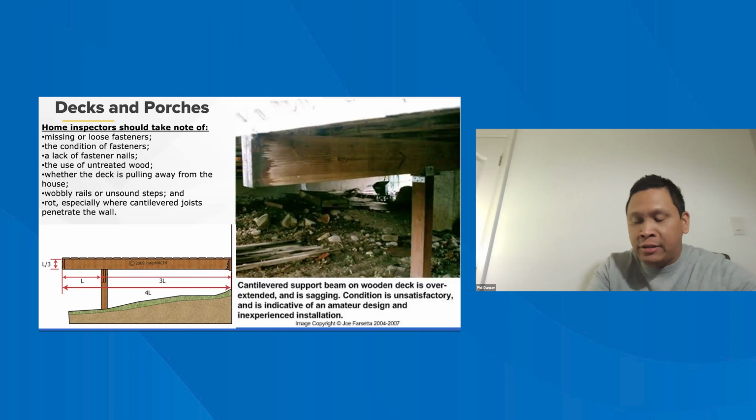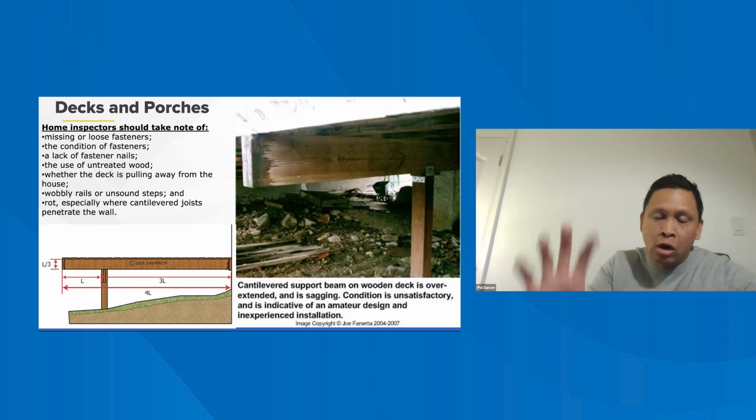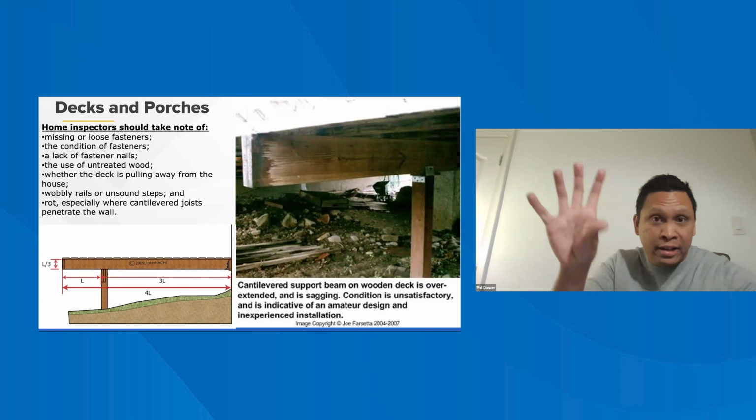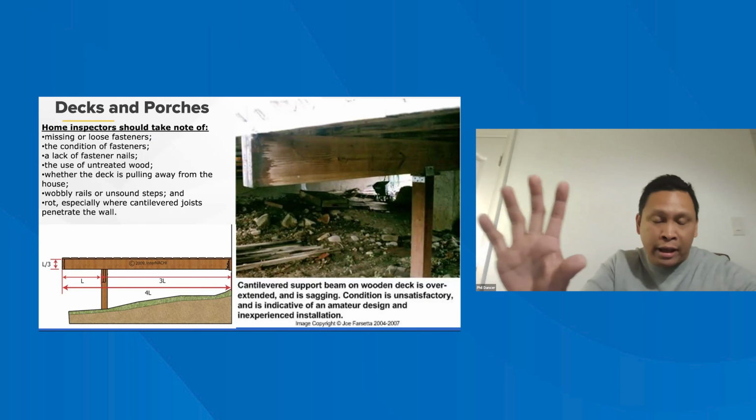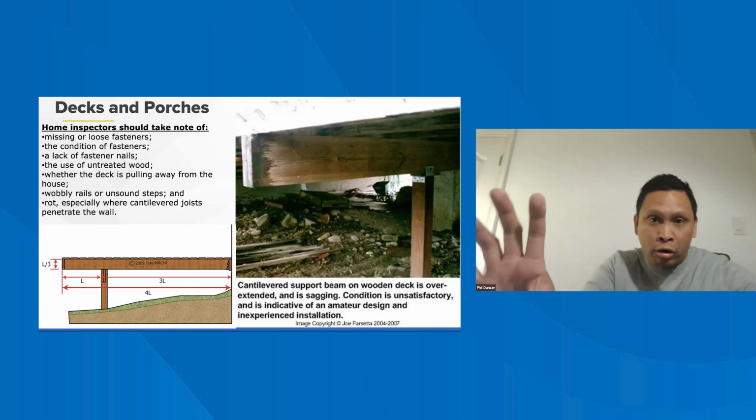One of the other things that I see that we wouldn't be able to see on a resale, because we've got the drywall up in the house already, but what you might be able to see when you do a pre-drywall inspection, is when the builder and their subcontractor, their vendor, is installing the ledger board to the house. One, we want to make sure it's directly attached to the house, right? So we don't want it attached to the siding, that can make the ledger board move.